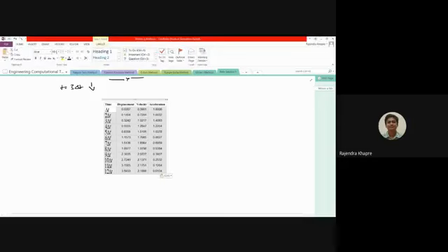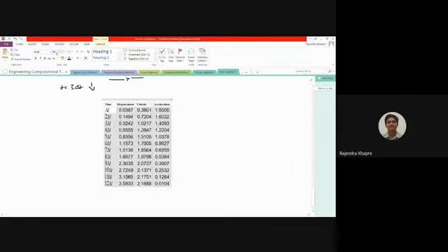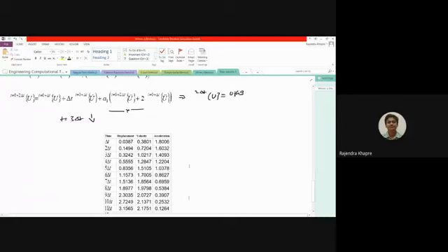Here you can see again the displacement is increasing, the velocity is also increasing, whereas the acceleration is decreasing with the increase in time. The response is very much similar, only the values can be a little bit different if you compare with other methods. So this is how the Wilson theta method is going to work.